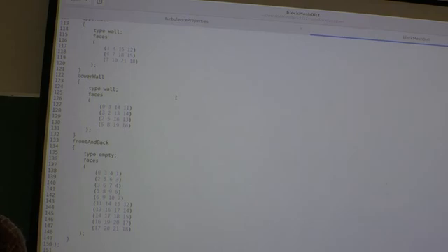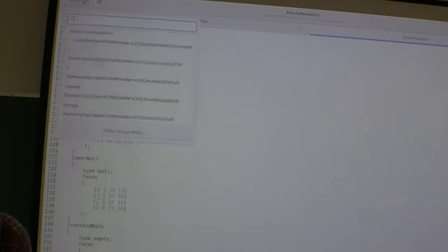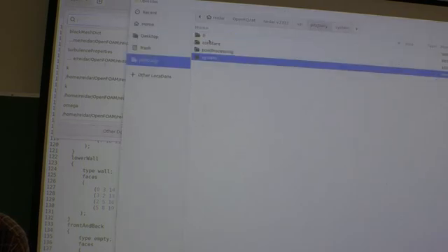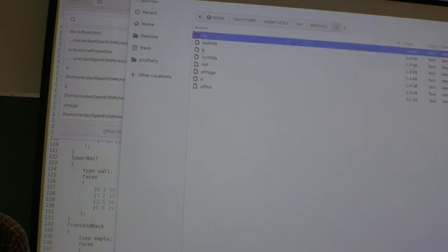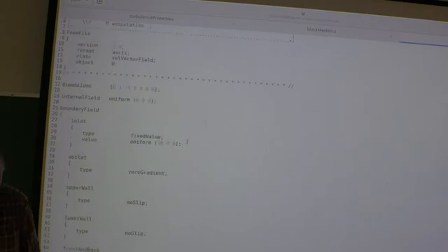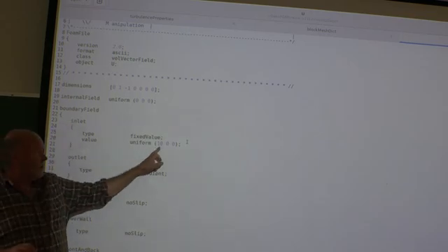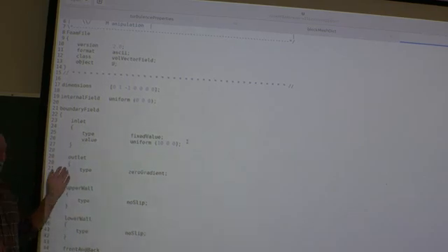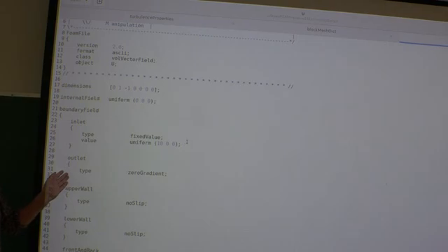So let's have a look at some of these zero files. Velocity. Okay, I send in, as you can see at the inlet here, 10 meters per second in the x direction. Okay, outlet, I have no idea, hence zero gradient.